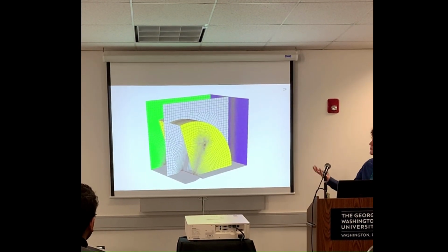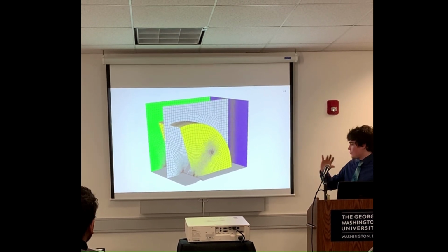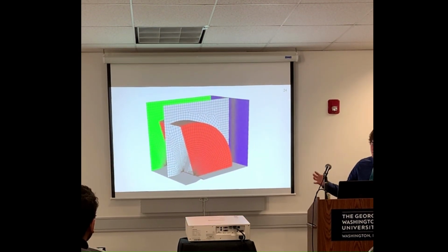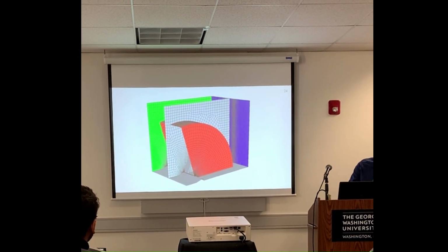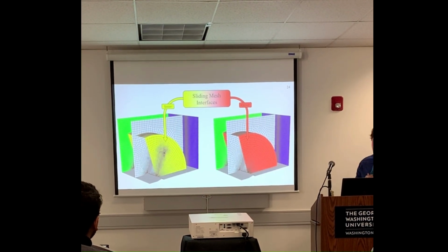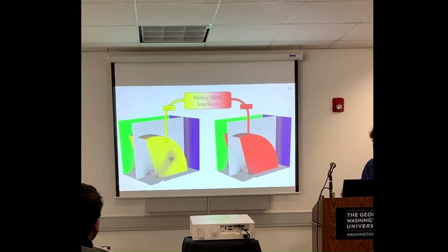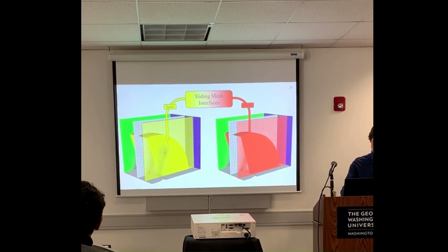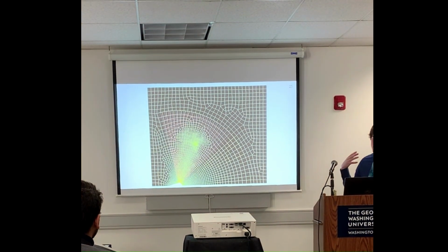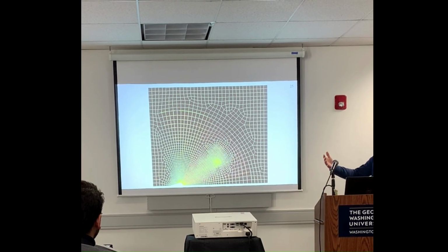The interior mesh surrounding the denticle itself is moving with the denticle, but the exterior mesh is stationary. So right here there is the sliding mesh interface, and that has the potential to mess up our drag calculations. Here's just another view of that. You can see the small yellow cells on the interior sliding past those red cells on the exterior.